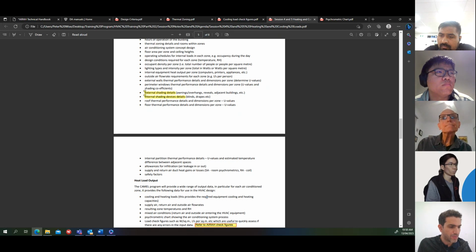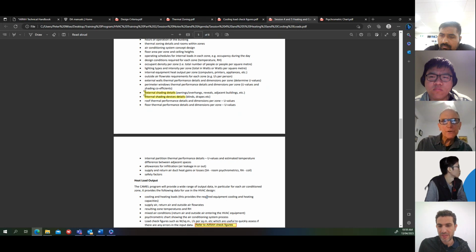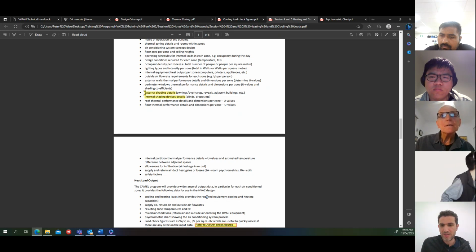And when you've designed, added up the whole building, let's say it's 500 kilowatts, for example, I don't know if that's something we'll discuss later. Do you select your equipment based on 100% of that load, or is there, I can't remember that factor where you actually select less because... So you're talking about diversity? Yes, that's the word.